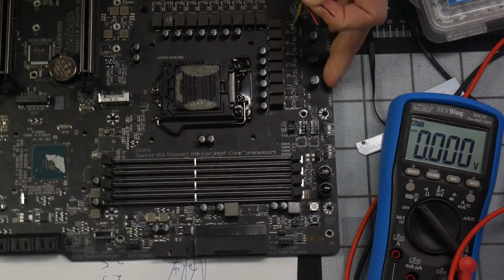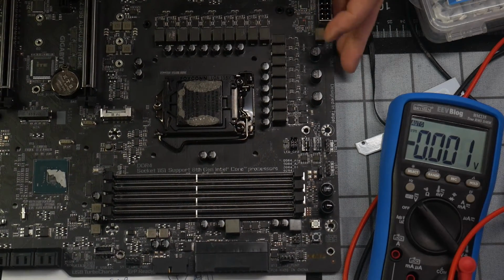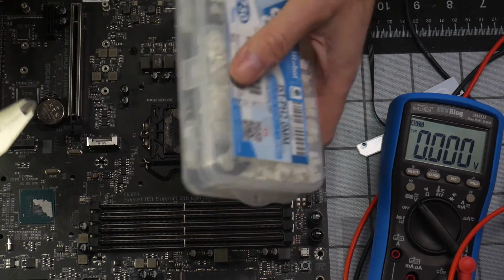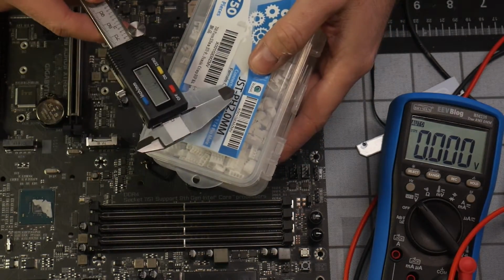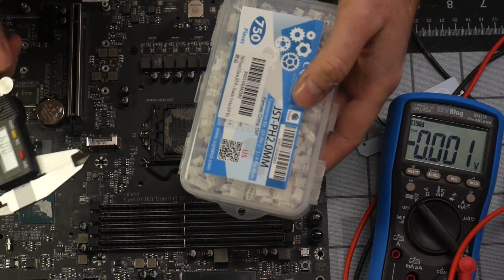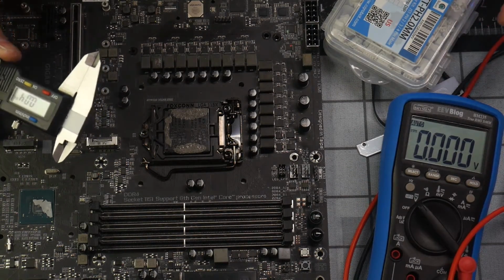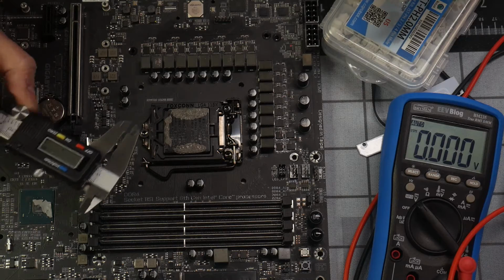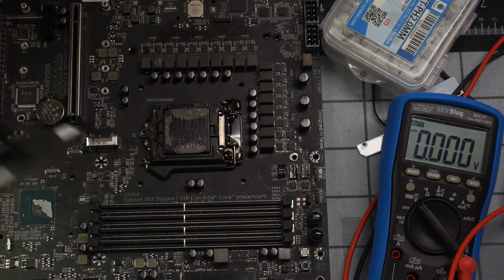Might look that one up, I might not. This board is dead, so I'm not going to really mess with it any more than that. But you just use calipers, look up and see if there's a JST one that looks similar, and whether it's a JST Pico or PH or SM, or all the different numbers and letters that they have put together. Just try to measure it and look up a 4-pin JST PH and a data sheet, and the data sheet will show exactly the measurements. Compare it to what you measure with calipers, and you can find if it's correct or not. That's kind of the best way to do it.